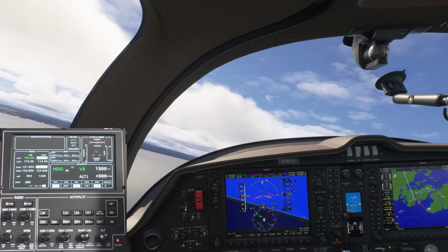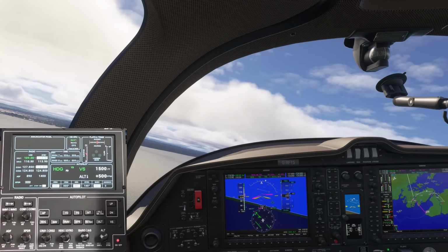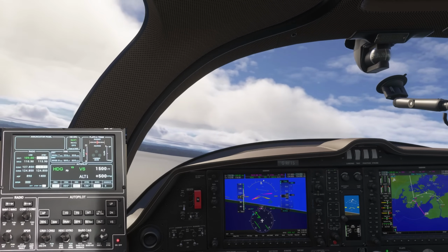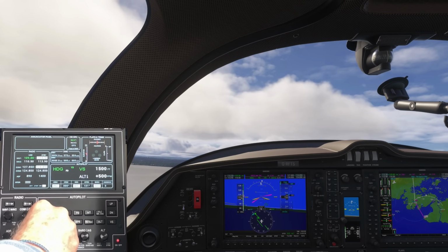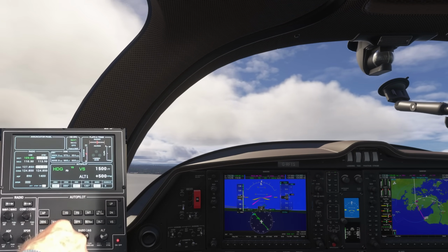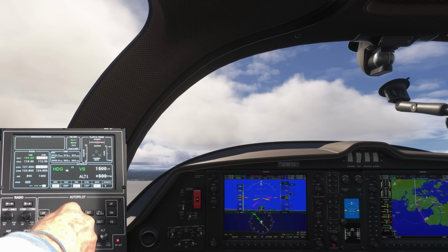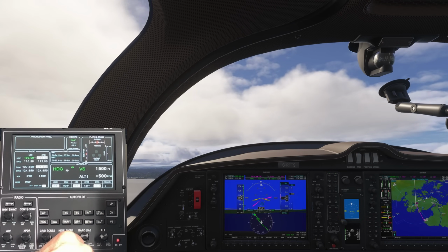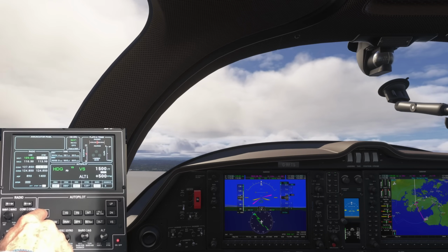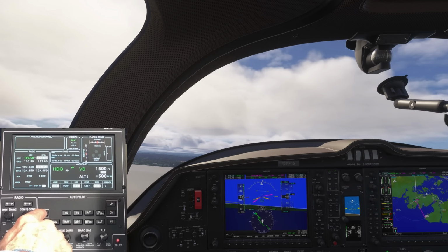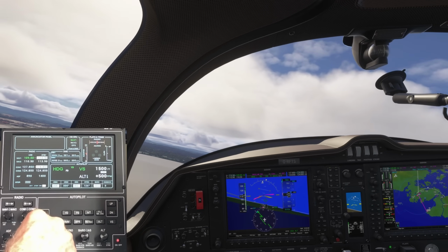Time to head towards the VOR, so I just need to adjust the course so I can dial in my heading. Then we'll get onto autopilot. Moving the course needle to bring the deviation bar central, that's about it. Adjust the heading, looking good. Pretty much set up now, just gonna turn more to the left, and then we'll engage the autopilot.